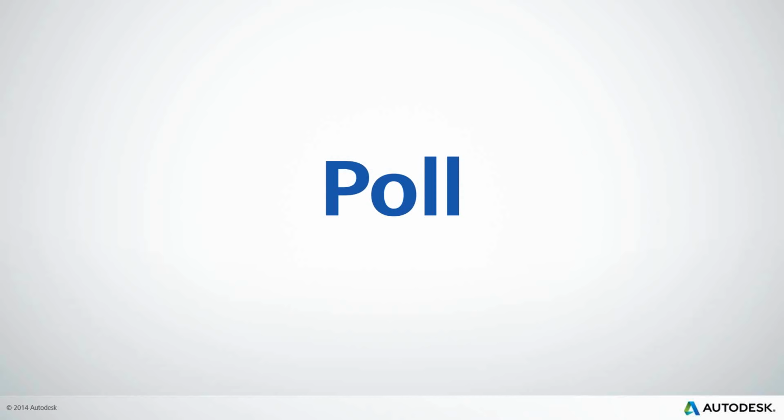That's a great question there, Beth. Thanks for bringing that up. It's really hard sometimes on thin parts if you really want to see the details and mesh to 3D to accurately capture it and get a good element count through the thickness of the part while being able to reduce that aspect ratio. What I would recommend is take a look at the help file. It does list the recommendations for aspect ratios in there.